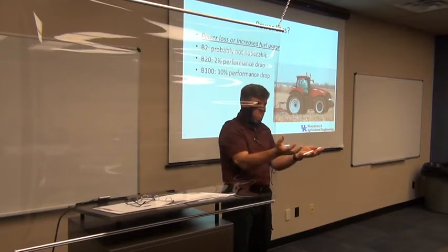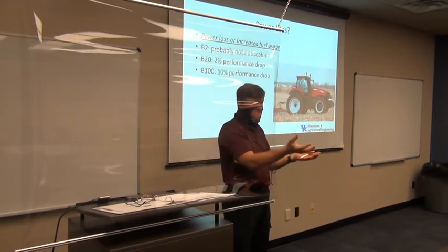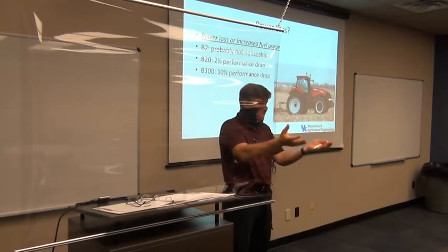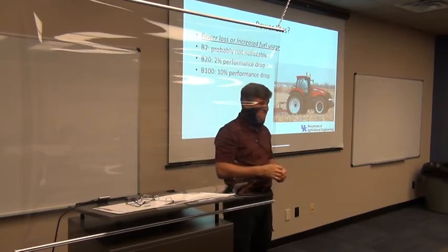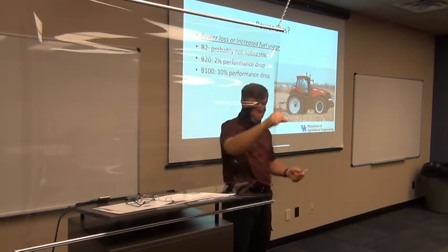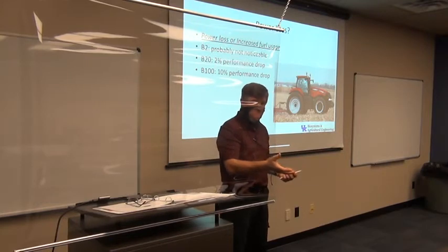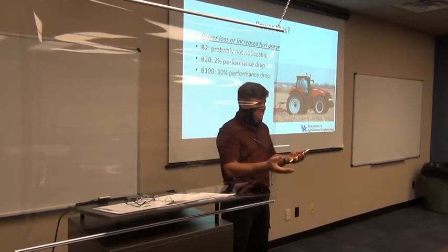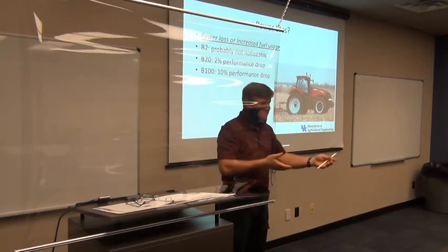What do you think the difference is in the physical properties of that cooking oil and diesel going to be? Any guess on that? Viscosity going to be the same? No, probably not. Viscosity going to be higher or lower? Pretty high, yeah. So it's going to be thick. You pour cooking oil out, you get this glug, kind of slow. Diesel is pretty similar to gasoline. You spill gasoline on the side of your car, it's pretty thin. It runs, it's more like water. So there's going to be a viscosity difference. Might that respond differently going through the fuel pumps, through the fuel system on the engine?